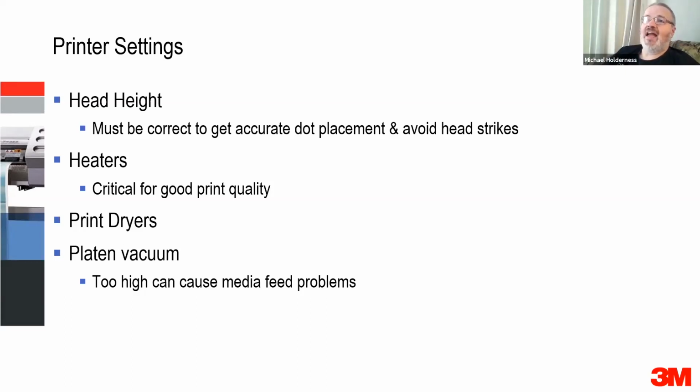Latex printers will have their own calibrations as well. Latex heads won't last nearly as long as a solvent head, but latex inks are much cheaper. Latex heads are much cheaper. It's a few $100s as opposed to some thousands of dollars. I would, once again, be checking those regularly because those latex heads are more prone to blocking and won't last as long. But once again, check your printer manual.